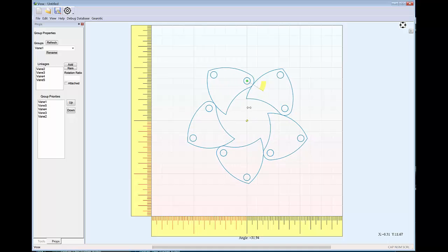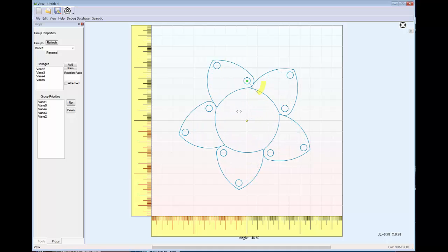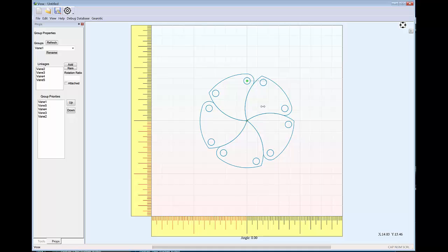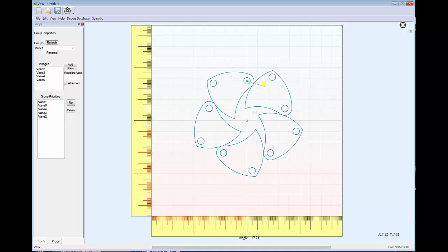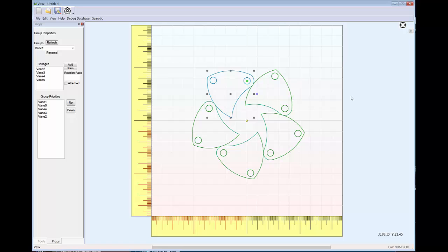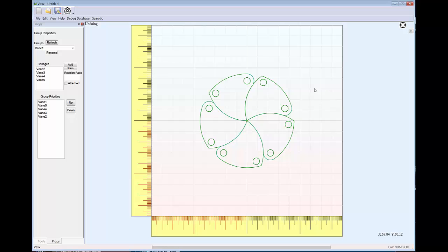If you like to keep things at 0 and you don't want to actually move it, and you don't want the pain of having to find exact 0 in order to lock them back to 0, press your control key, and when you release your mouse button, no rotations will take place. They'll simply go back to where they were. Now, should you forget to do that and you rotate them out and release your mouse key, and all your vanes are now in these locations, you could always use Control Z to go back as well.